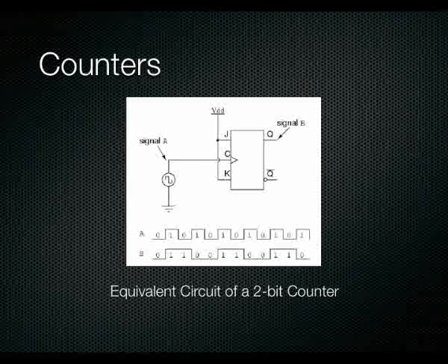And then, of course, it toggles back to 0 again. So then we start back at 0 again. And then we go 0, 1, which is 1, 1, 0, which is 2, 1, 1, which is 3. So it simply counts up 0, 1, 2, 3, and then it rolls over. Okay, so counters are a very good way of incrementing variables. So we simply have a JK flip-flop, and every time we pulse it with a clock, it simply increments.